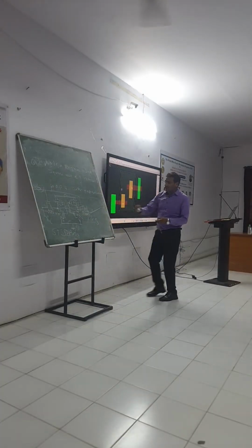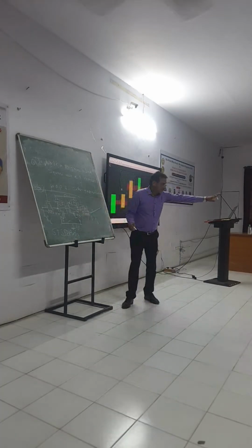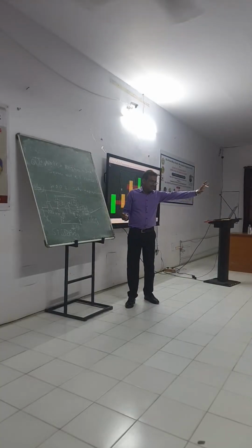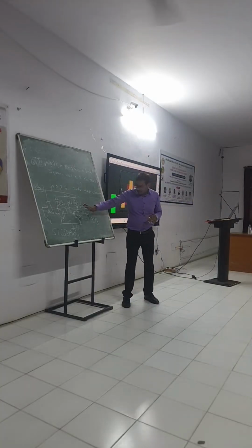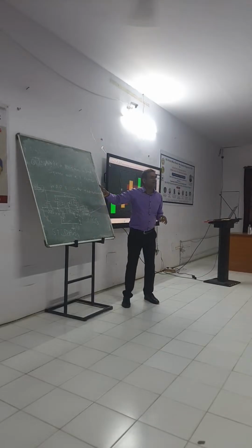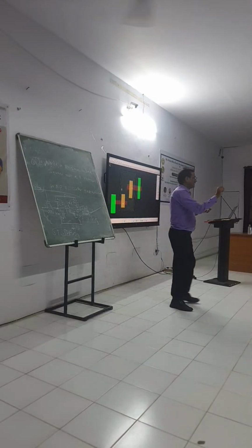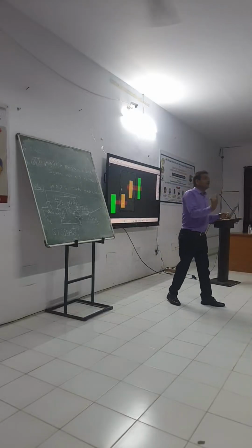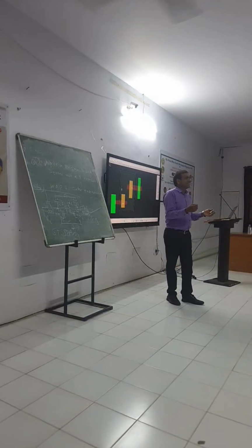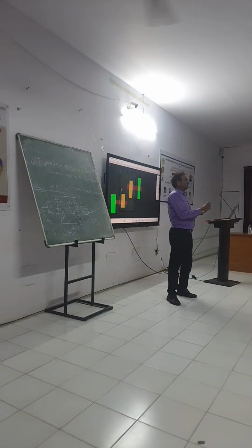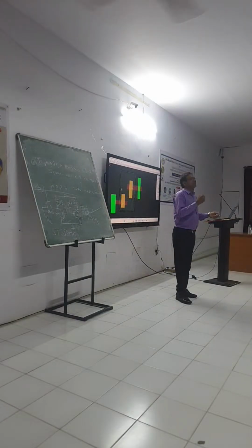So sizing also I taught. Those who trained in the 6T SRAM class, I taught sizing is also important. If you are taking proper sizing, technology is fixed like 60 nanometer. Width we are changing because aspect ratio you have to select properly so that its switching will be proper.